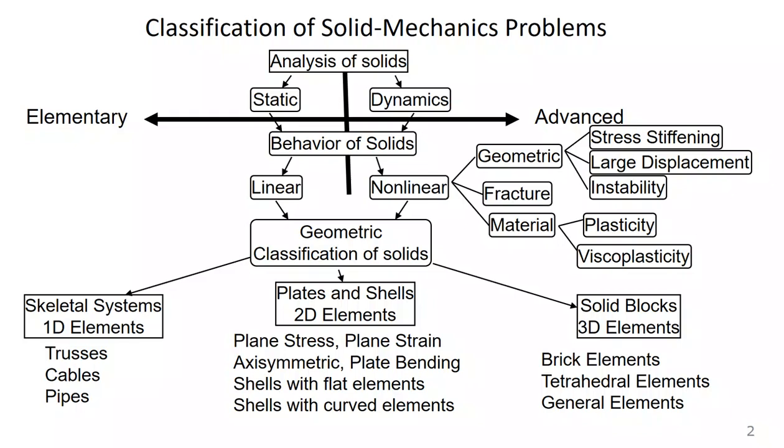For example, if there is a sharp corner, the stress concentration will be very high. So for that we provide fillets or a fillet radius, which changes the stress distribution throughout the surface. So the stress concentrations are very high based on the geometrical structures.